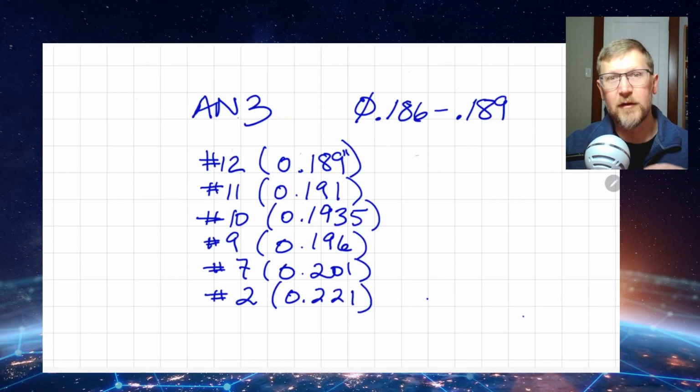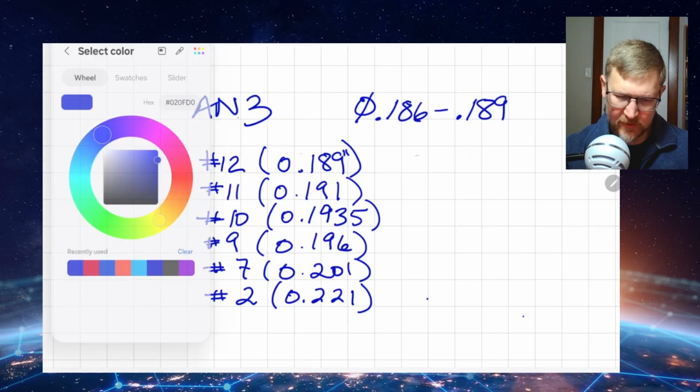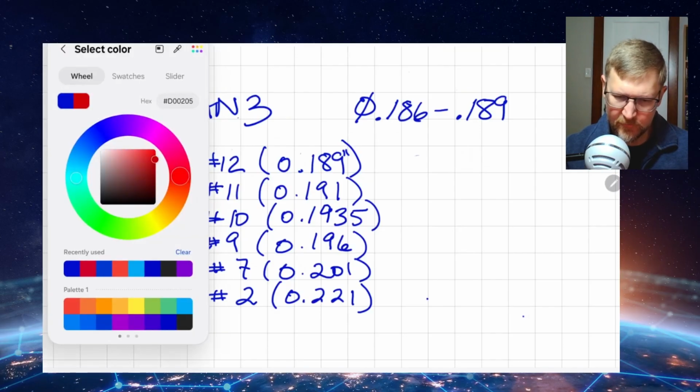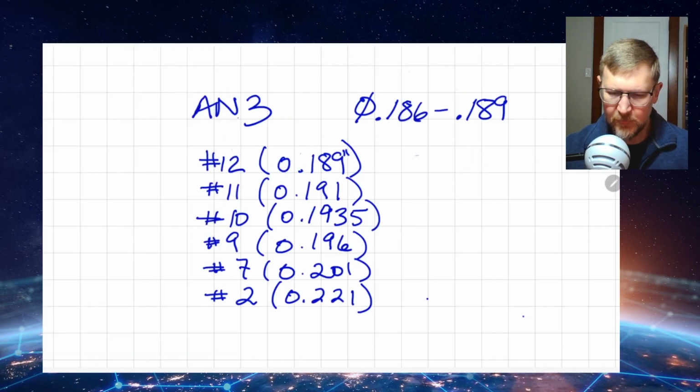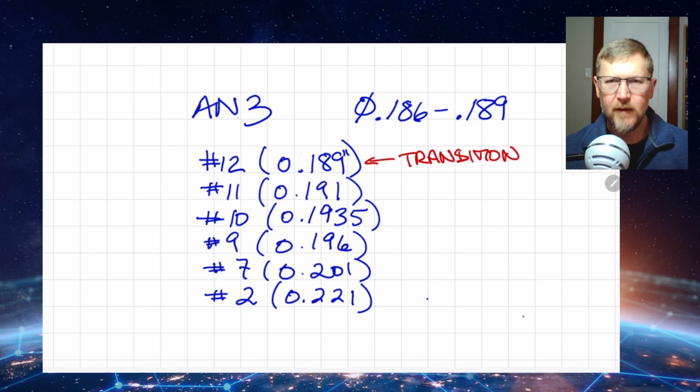These are kind of common drill sizes that you see in a range that might be useful for a fastener like this. So why might you want to choose any particular one over another? Well, like we said, this is probably kind of like a transition fit.